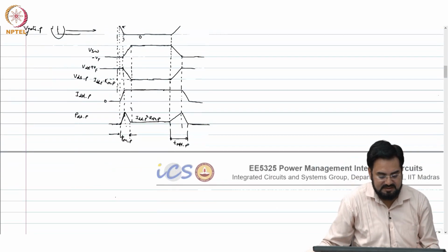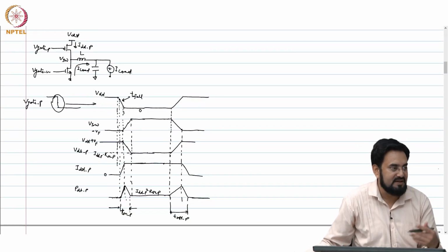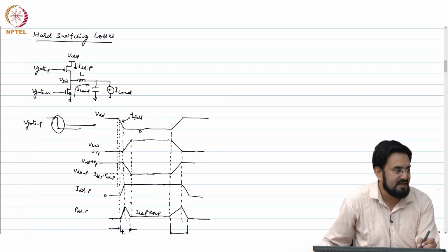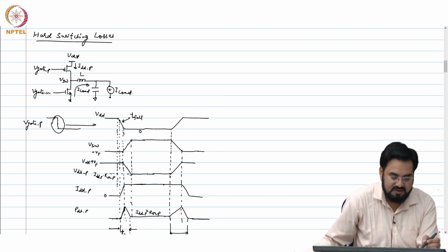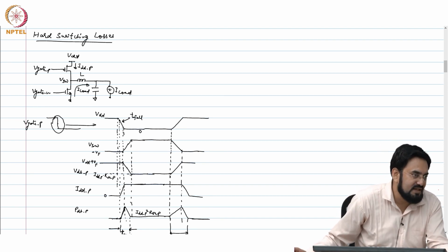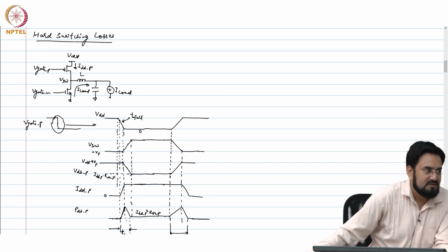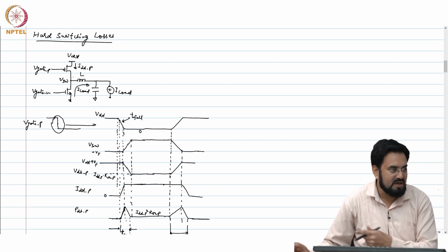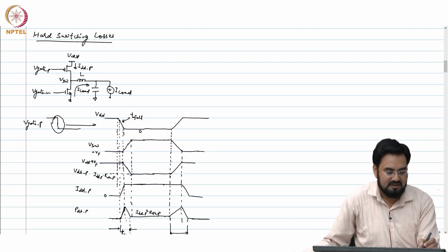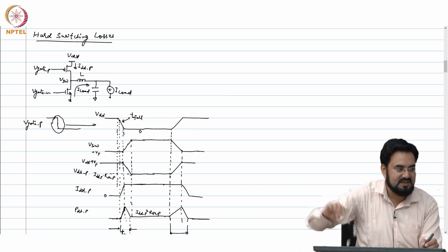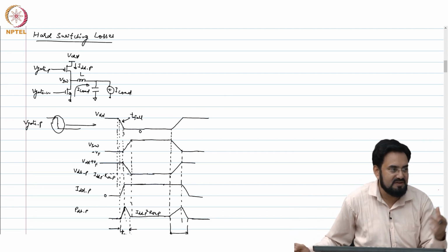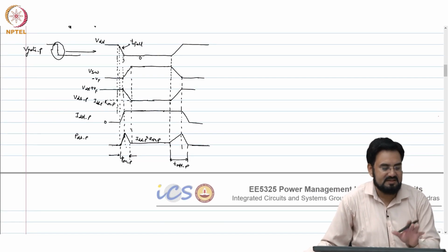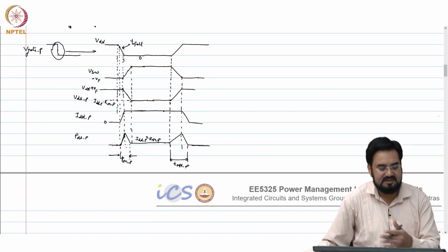So, the current starts, and there are some delays associated with the power FET, the intrinsic delays of power FET, which might be due to the parasitic cap at the drain, which is the intrinsic cap of your MOSFET, okay. And there are some parasitic caps on the VSW itself when you design. These are some routings, and usually this VSW is connected to the inductor externally. So, those pads will also have some capacitor. So, there will be some delays associated with that, but in the best case this is what you can achieve actually. In other cases it might be even worse.